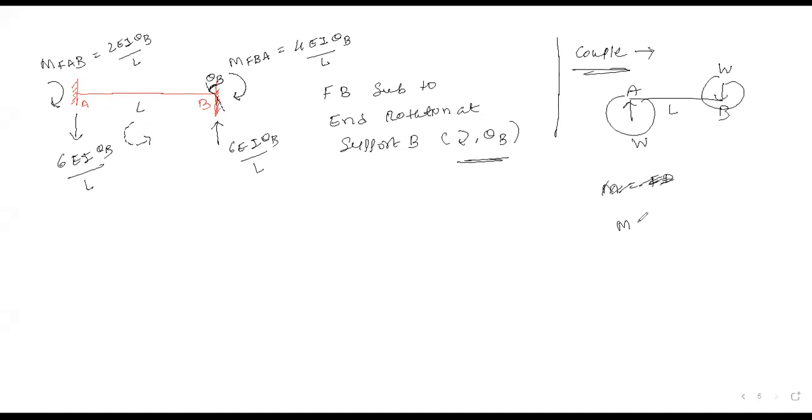Why? Just moment equals force into distance. We are interested to calculate force. What is your moment? 2 EI theta B by L plus 4 EI theta B by L. What is your reaction? Suppose I am interested to calculate moment at point B. So we have VA into L. Fine.